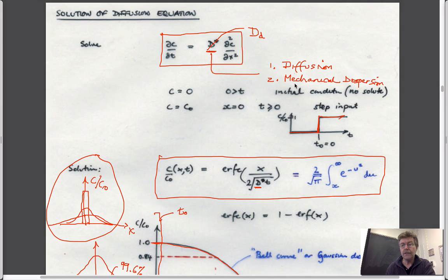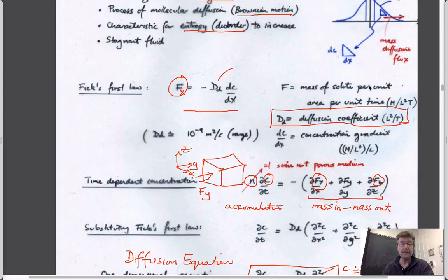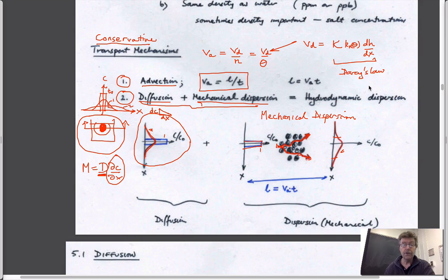And the reason we're able to do this is just going back to what we said here. If you look at the behaviors that you get from mechanical dispersion, it looks exactly the same as diffusion. It's just separated by some physical location where you're taking those measurements. It's like taking a beaker, putting a drop of ink in it, and then walking across the room to the other side, and then looking at what that distribution of concentration looks like. It's physically moved across the room, and it's diffused in that case by diffusion only.